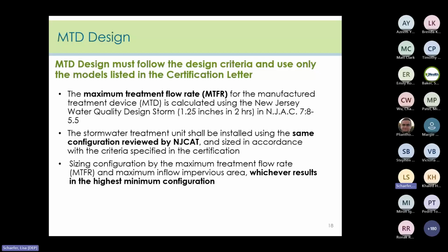All right, so if the sizing requirement in the certification letter indicates that the sizing is based on the maximum treatment flow rate or MTFR and maximum inflow impervious area, the model selection shall be based on the flow rate and the drainage area, and whichever results in the highest minimum configuration shall be chosen. Every certification letter has a sample sizing calculation illustrating the choice of a particular model.